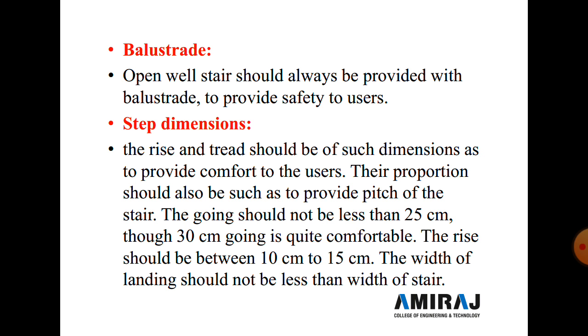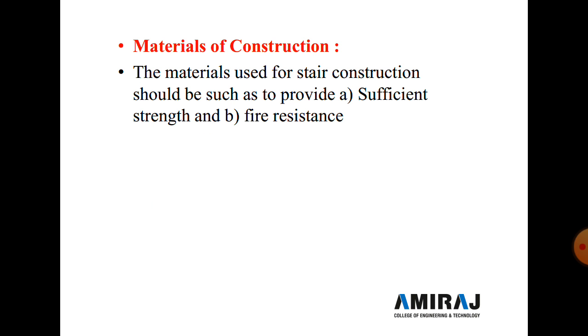The going should not be less than 25 centimeter; up to 30 centimeter going is quite comfortable, and the rise should be between 10 centimeter to 15 centimeter, and the width of the landing should not be less than the width of the stair. Generally 25 centimeter is provided, and 30 centimeter going is quite comfortable for the person.